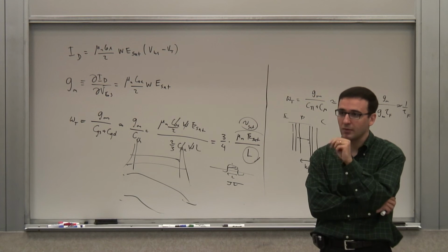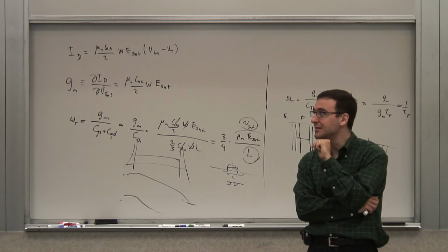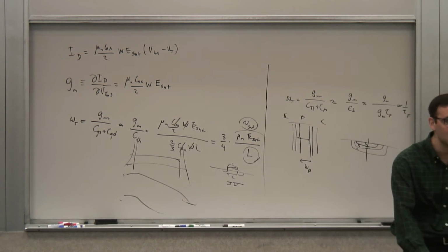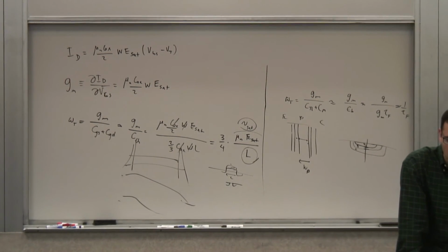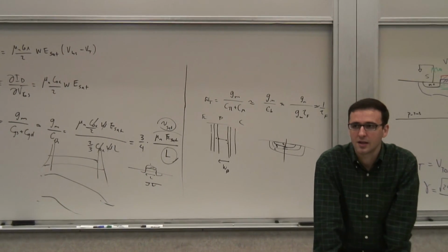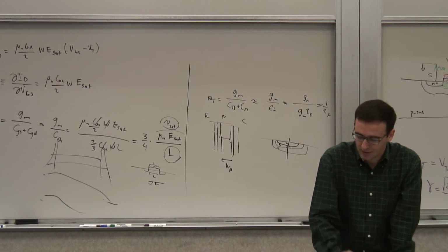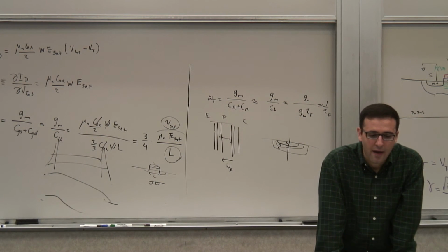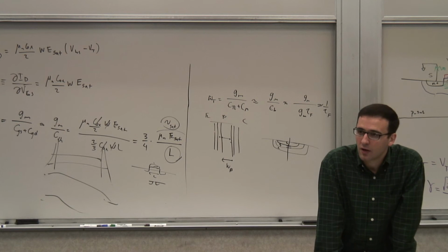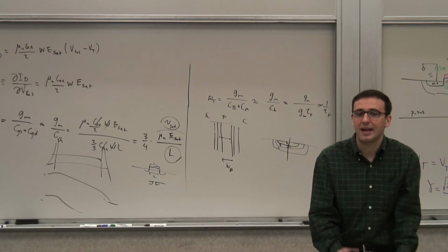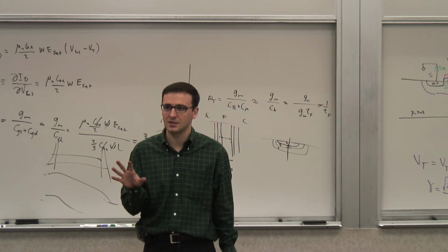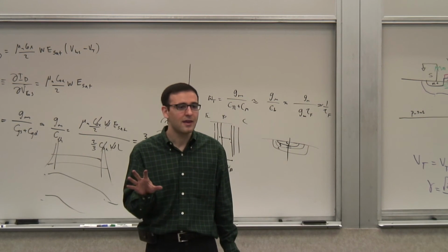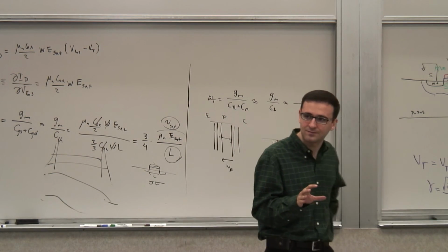You can make bipolar microprocessors, and people have made them in the past. But the kind of bipolar circuits that you need to make them fast are the so-called ECL circuits, and we'll talk about that. It's kind of something similar to that in analog. But they are power hungry. For every gate you have, they have basically DC power consumption. So even if you don't switch the gate, you have power dissipation in that node. Therefore, you can't have a very large number of gates.